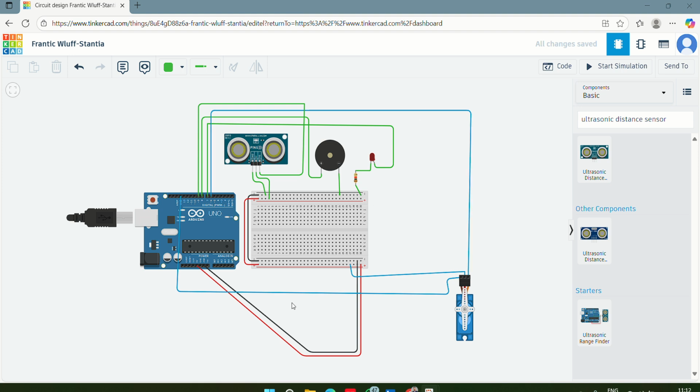What is the working principle of that? What is the role of that? And how is it done with mathematics and physics? So the ultrasonic sensor continuously measures the distance between the UAV and the ground. The Arduino processes the data. If the drone is at the correct height, the LED glows and the buzzer pops up. If the height is wrong, a warning beep is given. At the correct height, the servo motor can also trigger the payload release.